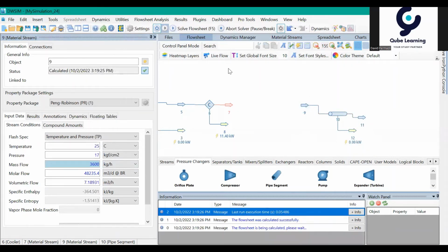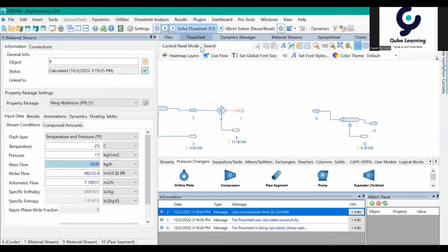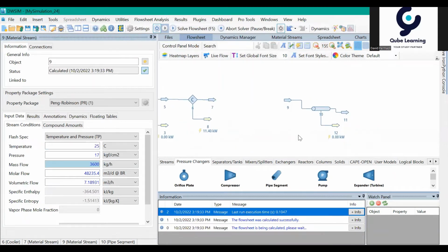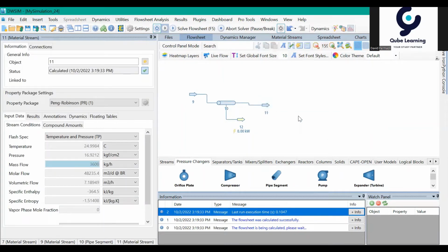Okay, that's all. That's done. Okay, why do we have to increase? Because the pressure drop is quite high, so we need to increase the pressure in the upstream. This is just a preliminary assumption, because we need to align with the downstream pressure, the destination pressure. Sometimes we need pressure regulating in here, so we have to add the control valve at the outlet of stream number 11.